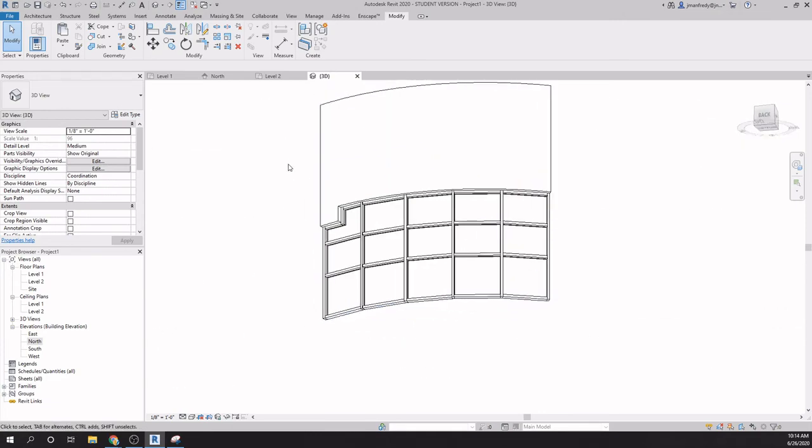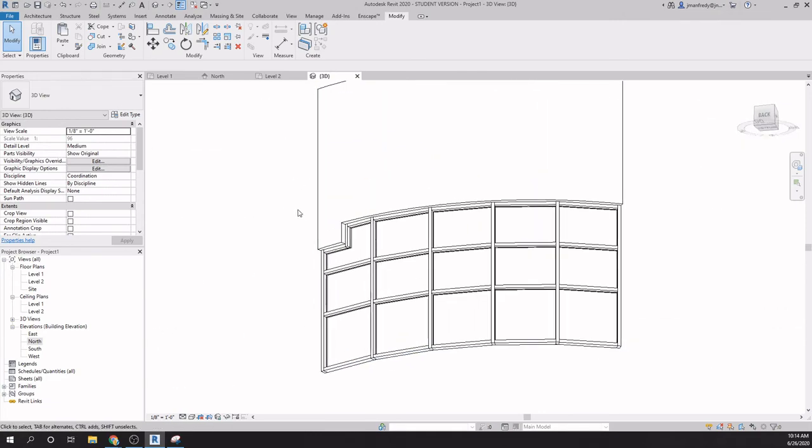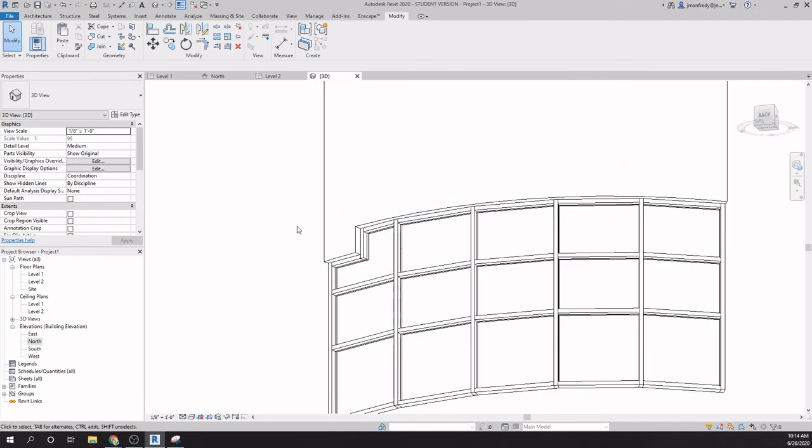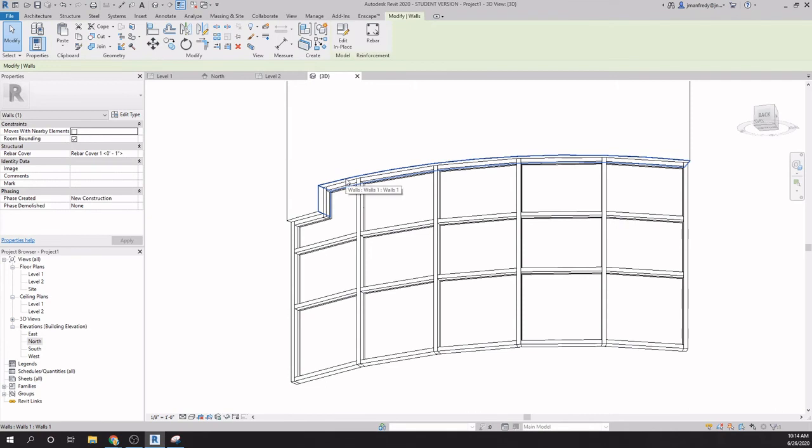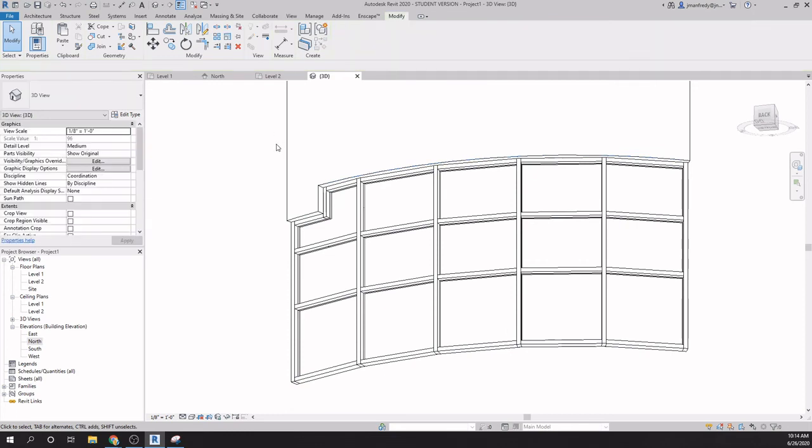If you need to modify that shape, that void shape, the object that's invisible here and is cutting out this opening, it typically lands on the edge of the opening. So if you put your mouse on the edge and hit tab, right there, click. Once you select it, it lets you edit the shape here, edit in place. So it's a little tricky because it's invisible.